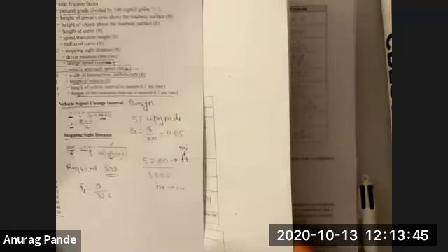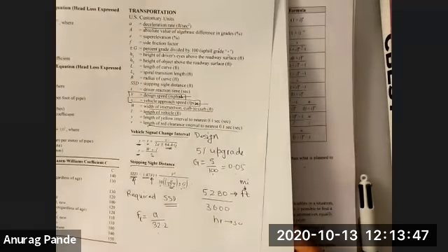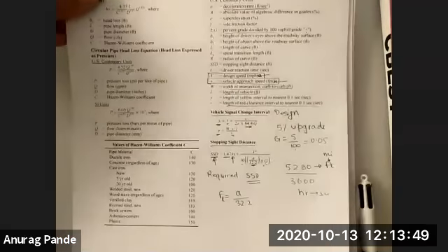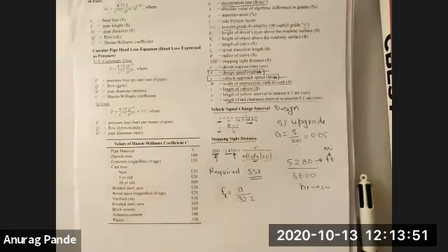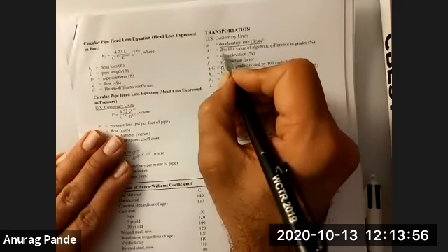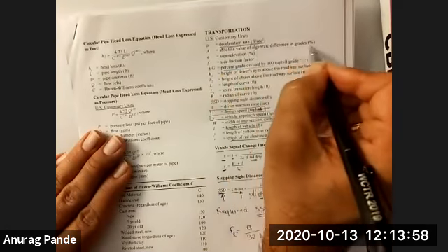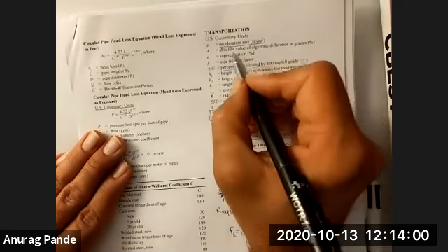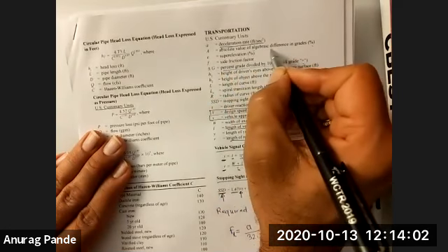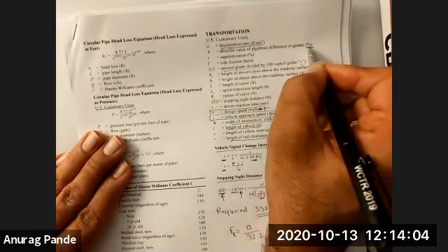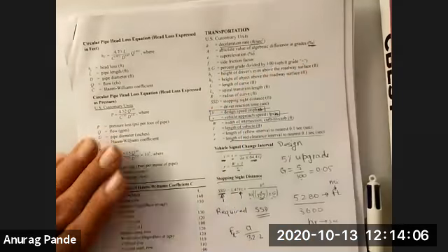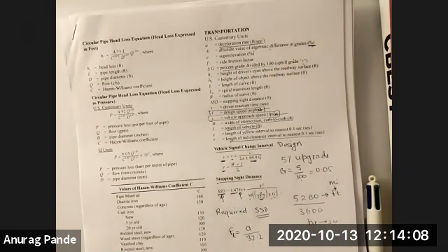Let's see where that is defined. Capital A is defined where they provided the basic formulas on page 164. If you go back here, take a look at the absolute value of algebraic difference in grades. So capital A is defined as the absolute value of the algebraic difference in grades, in percentage. This is very important: the unit here is percentage. I cannot emphasize enough the importance of making sure that your unit is correct.